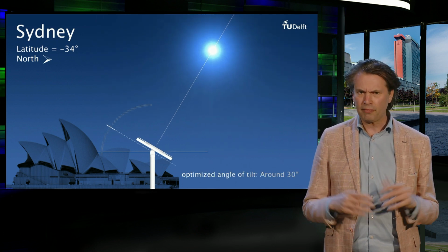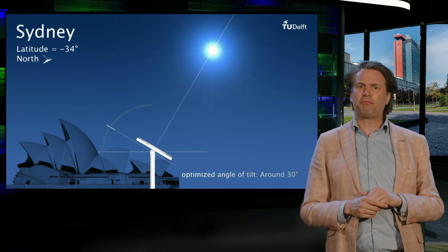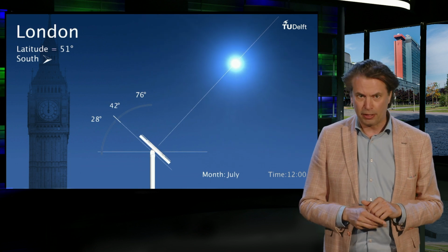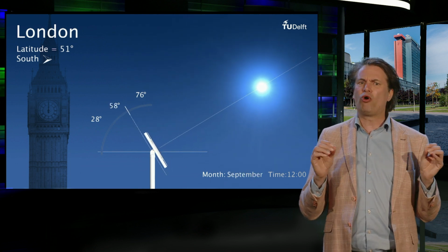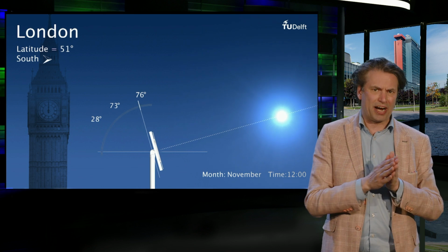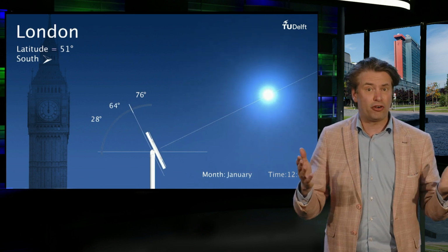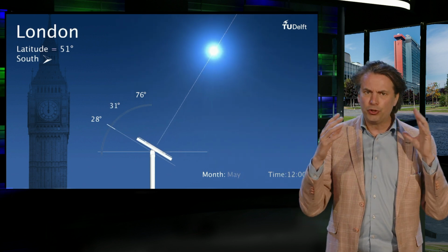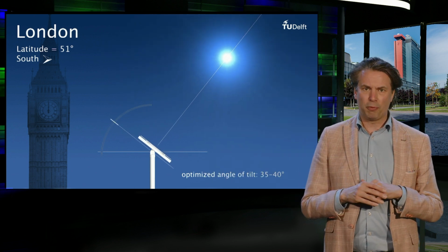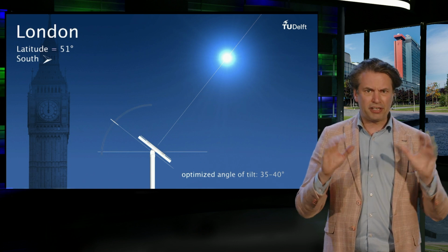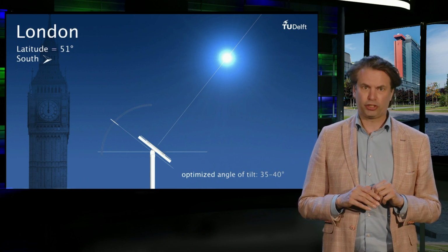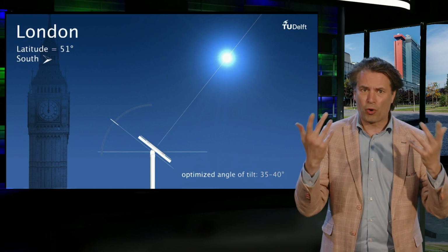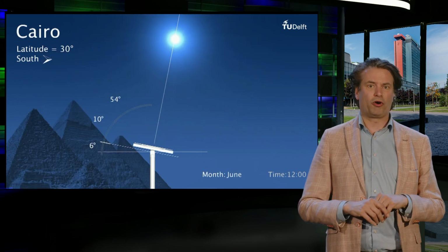north. It has been seen in practice that the optimized angles can give up to 70 to 80% of the maximum PV yield. As long as the solar panels are facing in the right direction in general, that is facing south for a panel in the northern hemisphere and north for a panel in the southern hemisphere, it is usually observed that the variation in the optimal orientation angle doesn't vary the PV yield too much. Consequently, the optimal tilt of the panels helps in harvesting more energy than the optimal orientation.